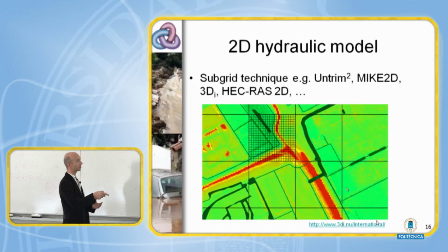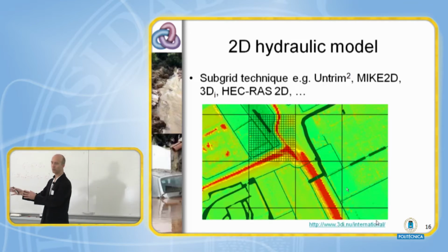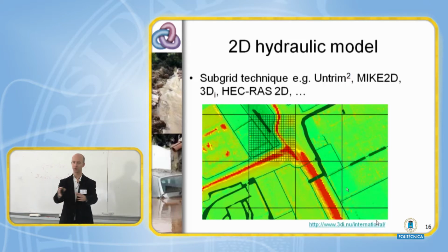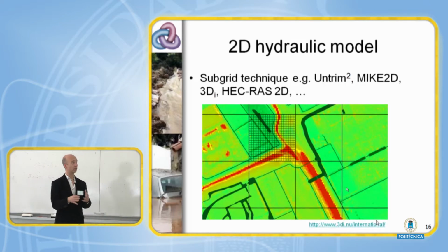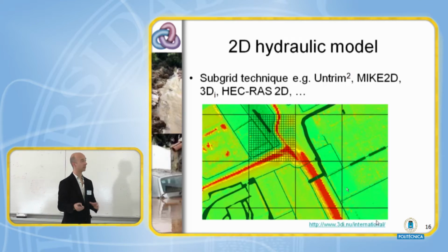So you just take the deepest part and you assume that that part is flooded. But if you have a grid cell that would connect two parts that are separated in the high resolution model, the water will magically move from one channel to the other. So you have to work on getting sufficient resolution to keep water basins separate.